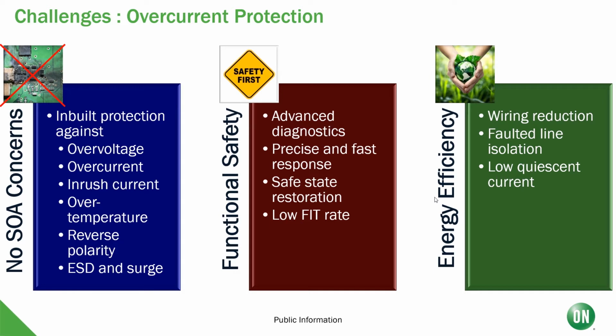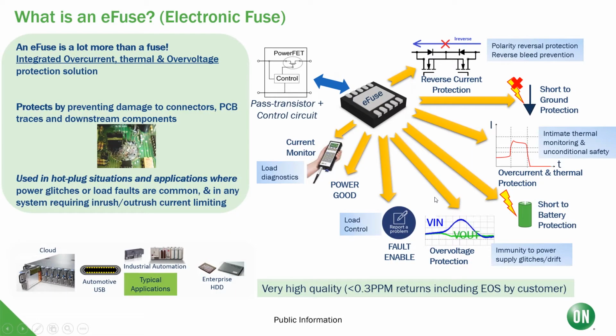Guaranteeing SOA is good, but an increasing number of end markets also require conformance to various functional safety standards. In order to achieve this, you will need advanced diagnostic features, fast response, safe state restoration, and low failure in time rate. Finally, while addressing the first two challenges, you need to maintain energy efficiency through low quiescent current, isolating faulted lines, and also indirectly save energy by reducing wiring. Traditional fuses cannot meet all these requirements, and that is where eFuses come in.